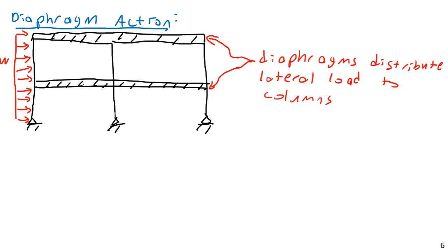But it turns out that when you build a concrete floor, a concrete slab, its main function originally is to gather the vertical loads, your live load, your dead load, etc. It needs to be so thick in order to do that that it also serves as a very good load distribution mechanism.